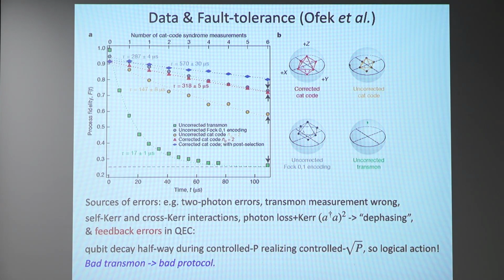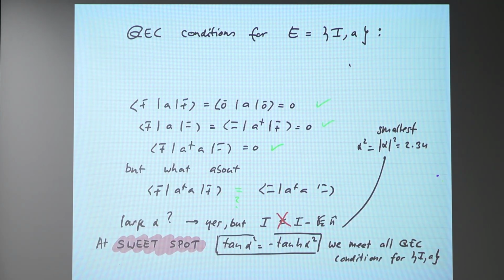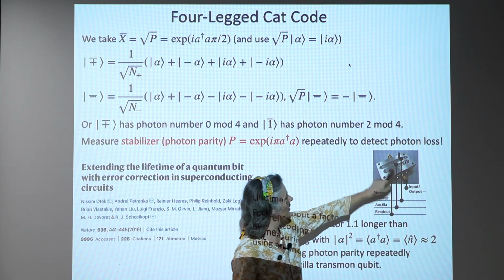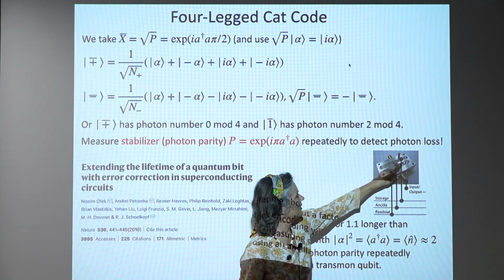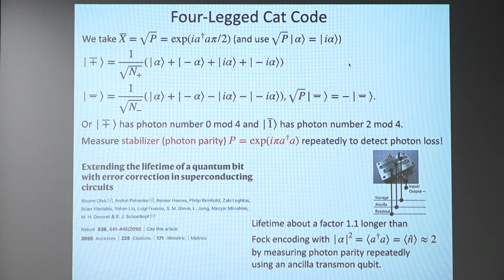Just to understand that setup, so the transmon is there in the system both to prepare your states as well as to read out the parity. Yes, exactly. And so to read out the transmon, there should be another readout resonance. Exactly, yes, and this is what's shown in this figure. Well, you can't see the transmon actually. These are the 2 resonators, and the transmon is sort of in between there.